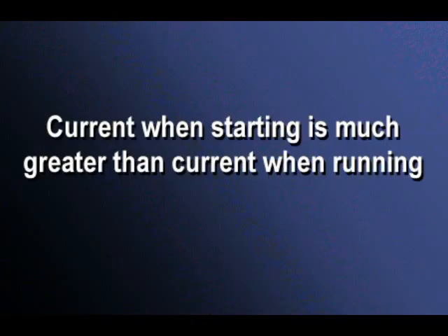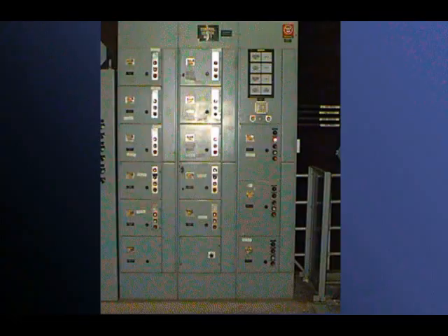The current required by a motor when a pump is starting is much larger than that required just to keep the motor running when it's already at maximum speed. To avoid a large current being drawn on startup, some large high-pressure pumps are started with no load. That is, no water is pumped until full motor speed is reached. This type of startup system is usually automated.